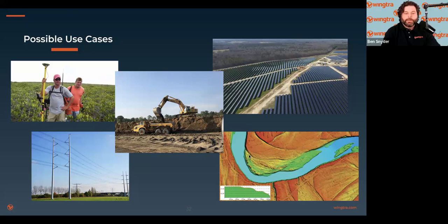And I see another question that came in. I'm happy to take this one. It was like, Wingtra used to be very anti-LiDAR and pro-photogrammetry, or so it seemed. It just shifted a little bit. Was this just a supply and demand decision? To take this, I think, most of the time, photogrammetry is going to get you 60 to 80% of the way there in many different applications. But what it can't do, LiDAR is able to fill in the gaps. So that's just my enough to be dangerous answer. I don't know if Ravi or Julian or somebody else would like to talk a little more about the relationship between photogrammetry and LiDAR.